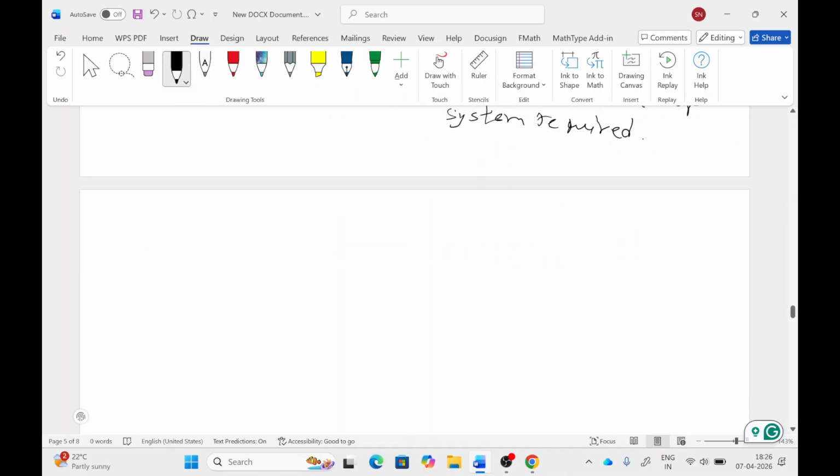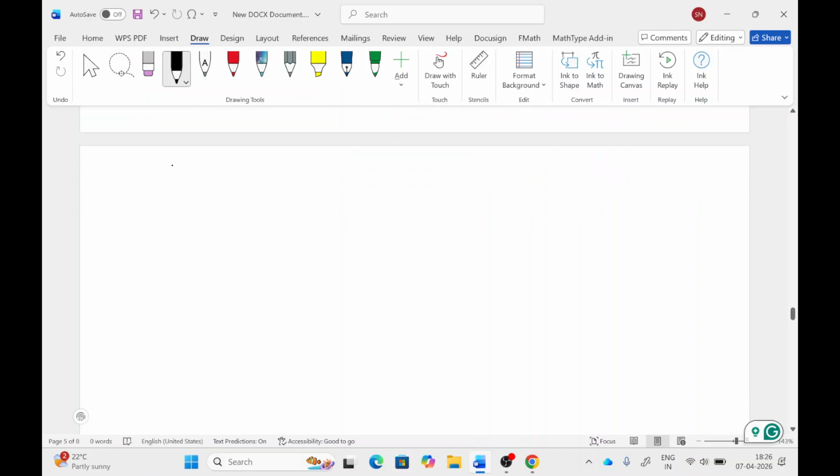Okay, so the Taylor hardening can be given as follows. These are the two dislocations, and the y and x distance between the two dislocations can give rise to a shear stress of around alpha G b square root of rho.